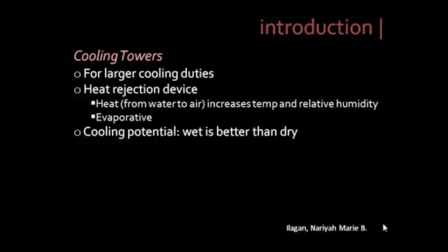It operates under the principle that the cooling potential of a wet surface is much better than a dry one, since the greater difference between the temperature of the cooling liquid and the temperature of the surrounding air yields a greater potential for evaporative cooling. The heat from the water stream, which is transferred to the air stream, raises the air's temperature and its relative humidity to 100% before being discharged to the atmosphere.